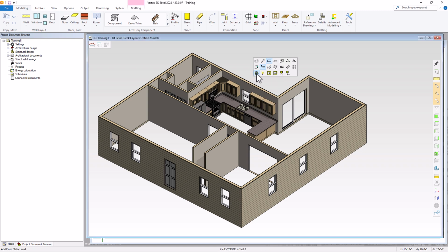When you select add using walls, you'll see a few more icons appear. You have this light bulb, which is find exterior walls automatically. Next wall. We'll select the next wall from a selected wall. Linked walls. Linked walls are continuous walls drawn in a single command. Next we have reference line. We can set the reference line for the floor edge, and then we can also offset the reference line by a certain distance. Let's go ahead and go through each of these.